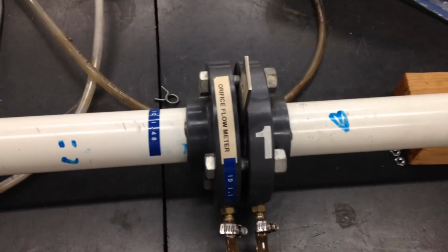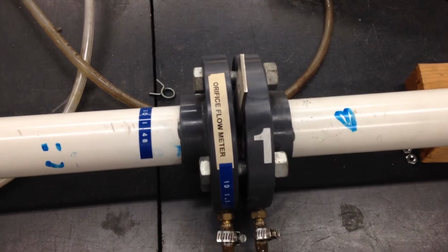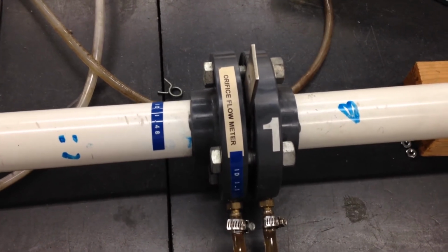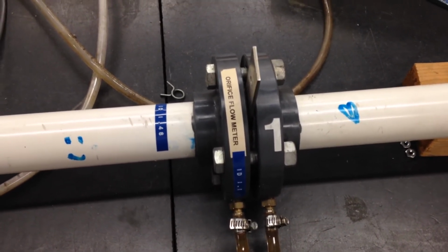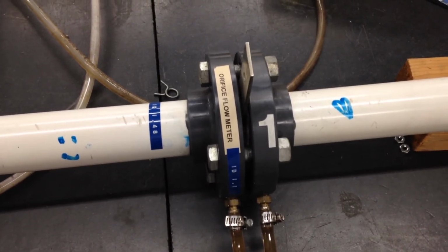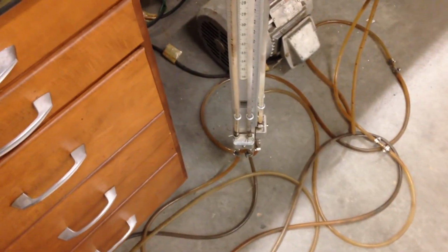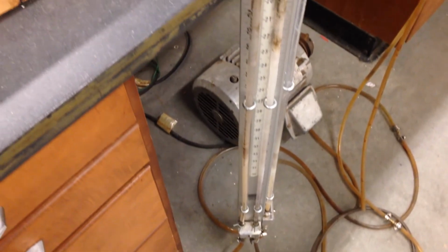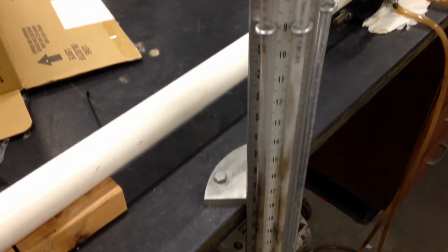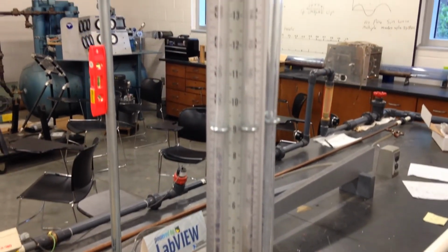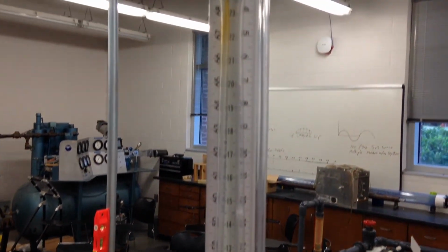We move on. This is the first orifice. An orifice is simply, as you see from my notes, a plate which lowers the diameter through which the water, in this case water, it can be other fluids as well, passes. Now you'll notice that there are two ports in the orifice, one on the upstream and one on the downstream. Those ports are connected to hoses that come around and back to this, which is a manometer. This is a classic two-tube manometer. It has seen better days, and you would be reading this to take measurements. In fact, you will be reading photos from it to take measurements on.